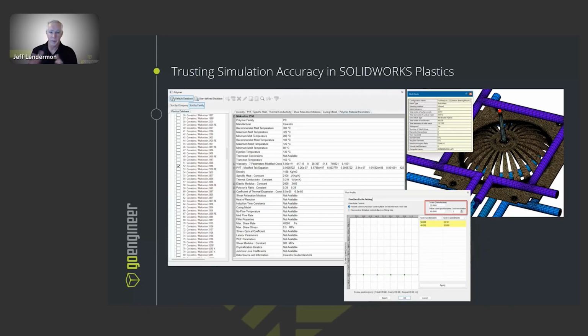But we have the ability to actually increase our mesh, have a more dense mesh than the coarse mesh, and still have the curvature refinement. So we want to make sure your mesh captures all of your geometry well. You don't want radius to show up as chamfers, right? So we want to try to capture the geometry as best we can, especially in thin wall sections around our injection location, those type of things. So we want to make sure that those have our best mesh.